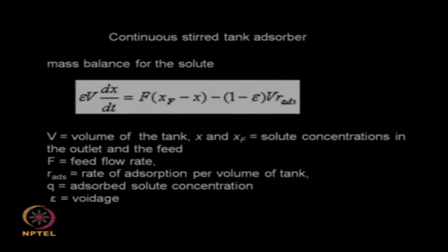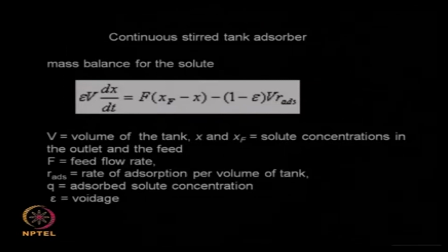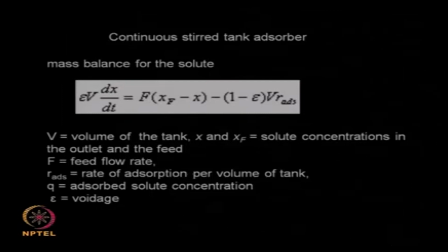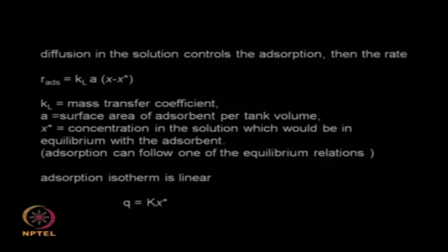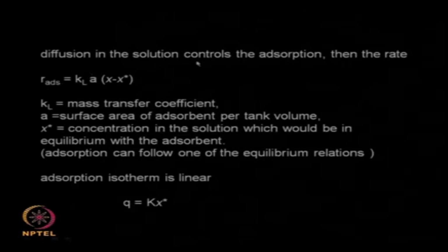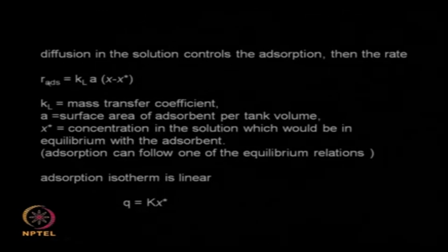All chemical engineers know that when there is a phase interface between a solid and a liquid, or a solid and a gas, or a liquid and a gas, then there is something called mass transfer. So that is what is going to happen. There has to be a diffusion of your solute from the liquid phase to your solid phase, and that rate is given by